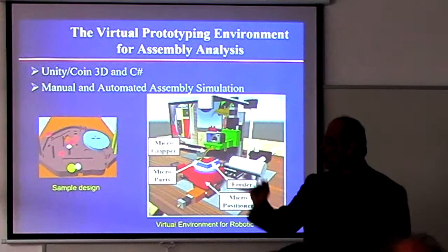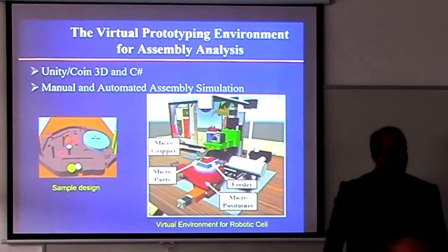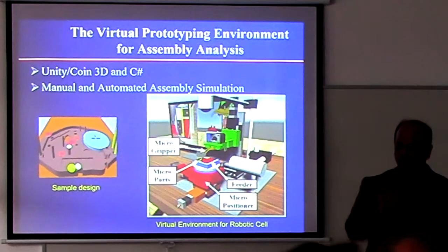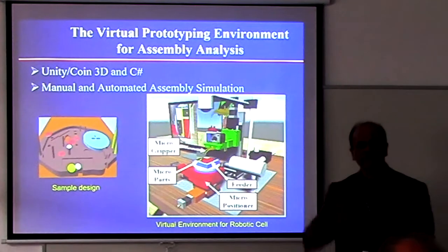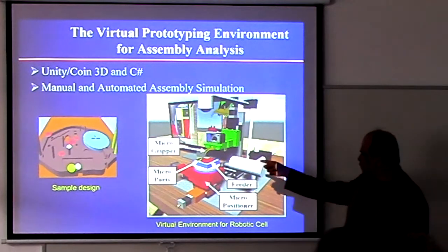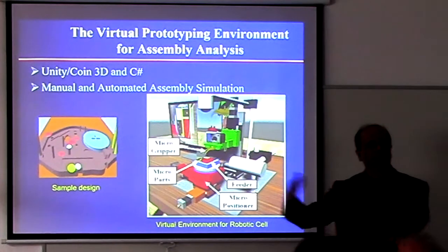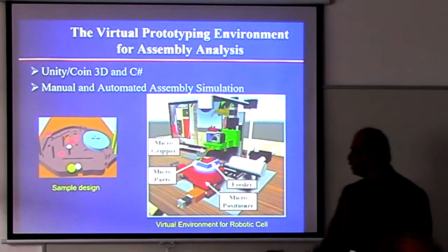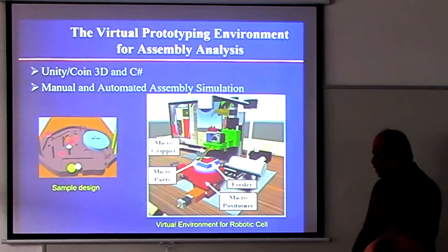So what did we do? We came up with a pyramid structure, the sawtooth, triangulation, right? And we said the point of contact will be just a point, but I still have relative gripping force. So this gripper has worked fairly well. We showed in different papers that the theoretical as well as the experimental results were able to be controlled fairly well.